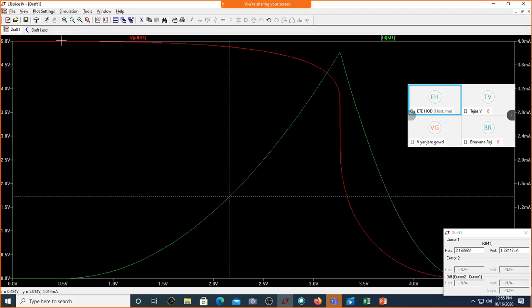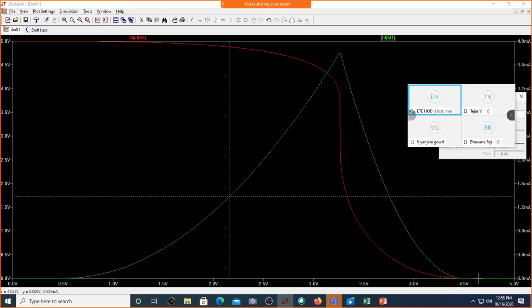Can you see the noise margin whenever the input voltage is low is more compared to the noise margin when the input is high? The margin is very little here, whereas in this case the margin is so much. But in an ideal case, whatever margin you have for the low should be the same as that at the high, meaning this transition should exactly happen at the mid of your VDD. We call the input voltage at which the output is also equal to it the midpoint voltage.